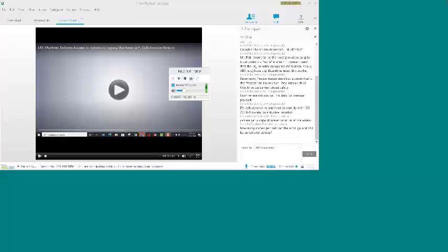That speed and separation distance I mentioned at the start, where you can have the robot running at full speed and someone standing, say, 8 feet away, but when they get closer, the robot goes down to 50% speed. They get closer, it completely stops. So that can be another option to get faster cycle time on your cobot by having that additional sensor capability installed in the robot.